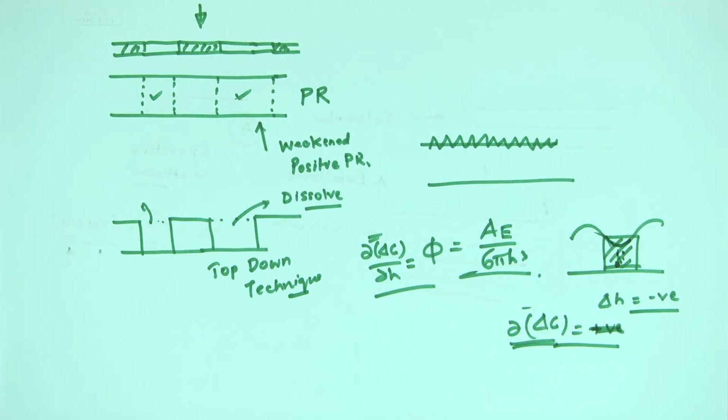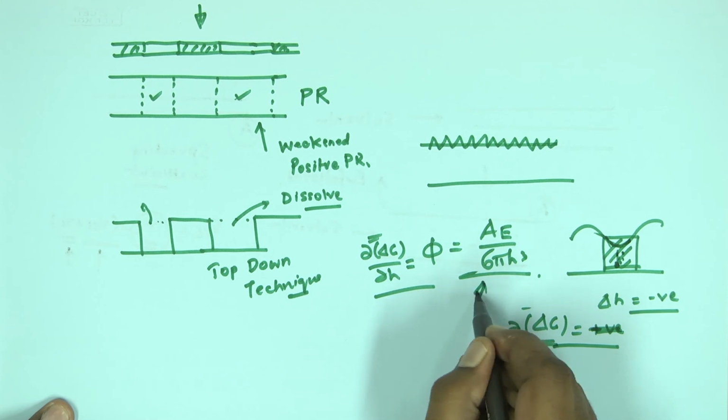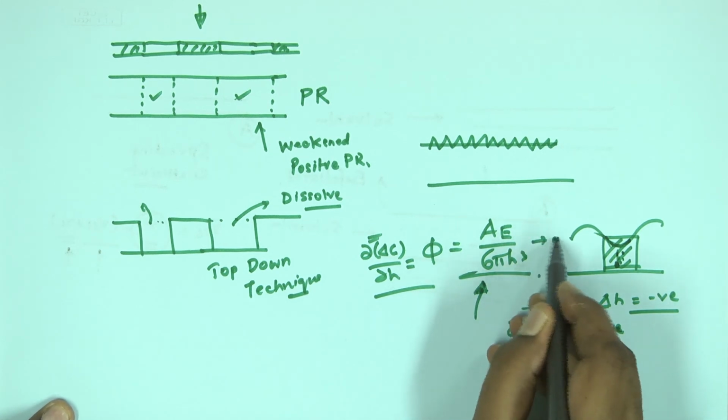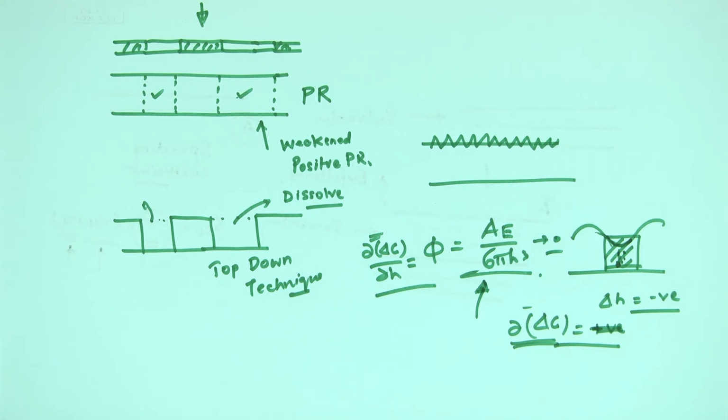Now of course you can clearly see that if H is large, right, this term will tend to 0. So whether you have a wettable surface or non-wettable surface, it really does not matter, right. That is exactly the reason why the films, if you want to have a stable coating, would like to have films which are adequately thick.